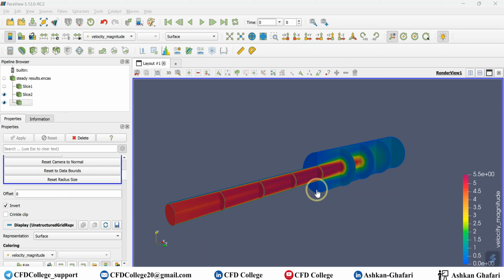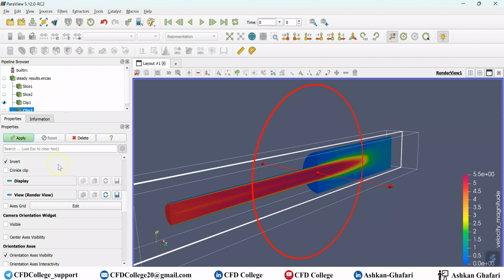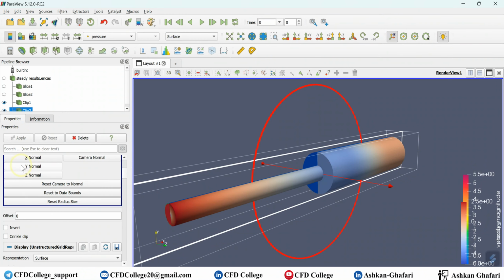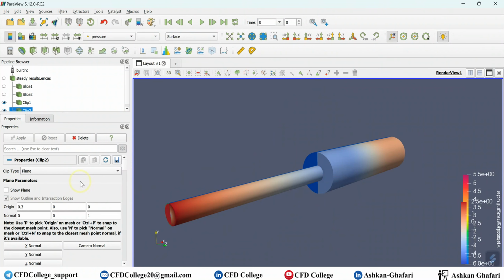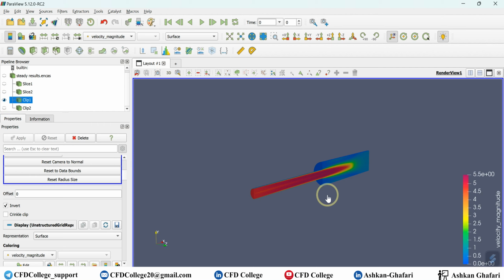You can create some exciting and interesting contours using slice and clip both together. Let me show you. Okay, we have one ISO clip for this side. So I add another ISO clip for the other side. Okay, that's good. And let me hide and show the first one.